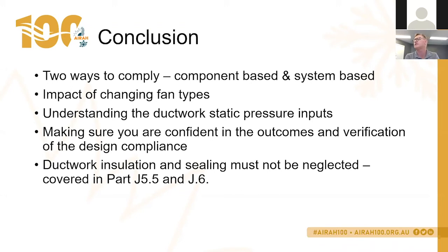Why is a fan in an AHU type A free inlet and free outlet? It's just the way the code definitions are set. The definition of a free inlet and free outlet fan is one without ductwork attached directly to the fan. So typically an AHU will have the fan sitting in a plenum or chamber, and then the ductwork will come off the plenum or chamber. So therefore it's free inlet, free outlet.